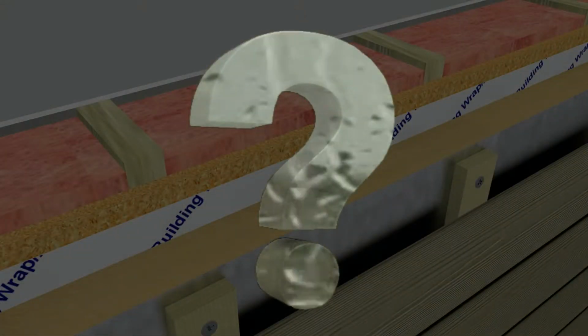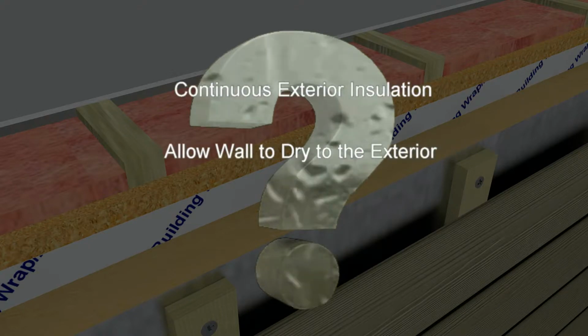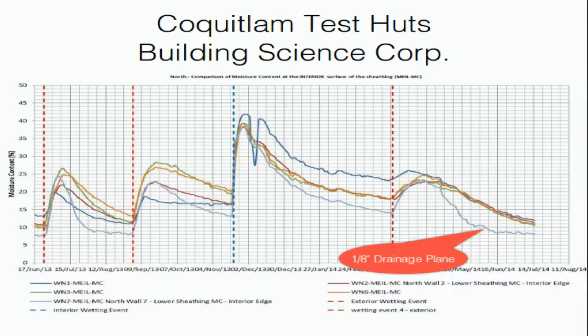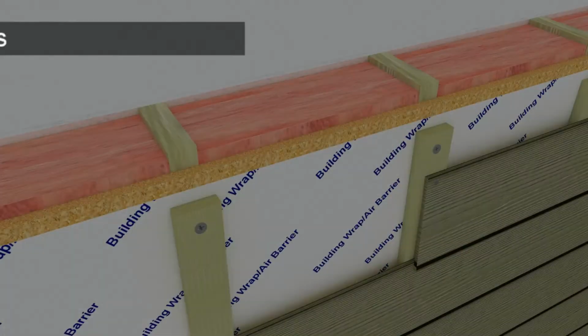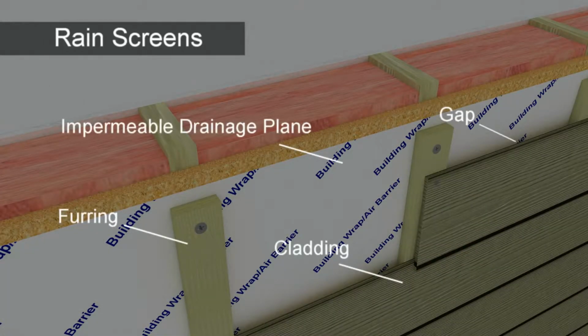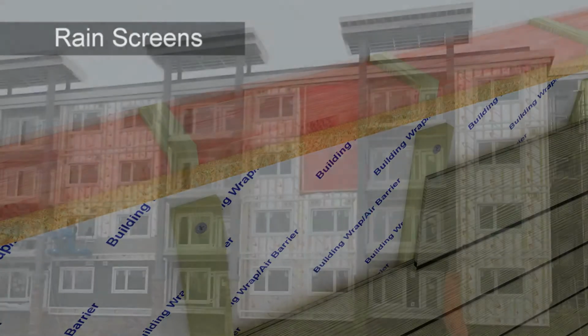So what would be the ideal solution that would provide continuous cover exterior insulation, but still allow the wall to dry to the exterior while preventing moisture ingress from the exterior? Tests performed by leading building scientists have shown that effective moisture redistribution and outward drying can be achieved in a wall assembly by providing a small gap between the sheathing and an impermeable or low permeable insulation sheathing. In addition, building science experts have also proven that Rainscreen assemblies maximize the service life of buildings by allowing walls to drain and dry, offering superior moisture management.